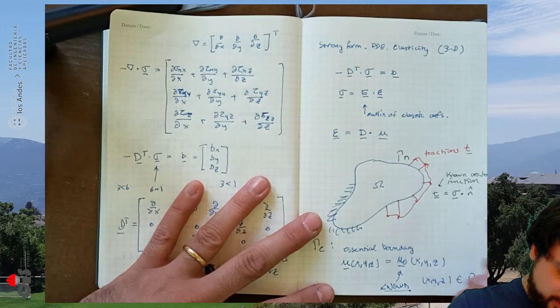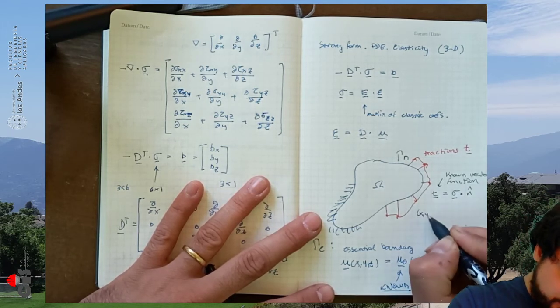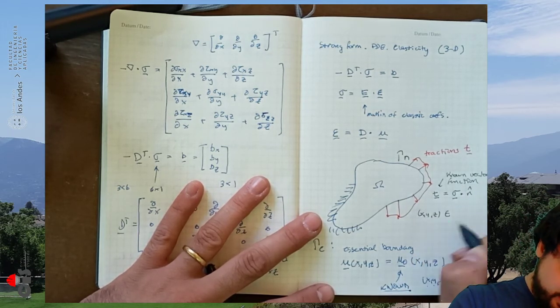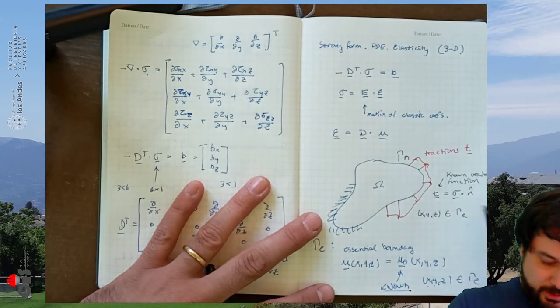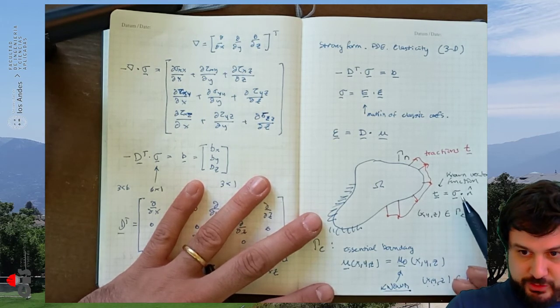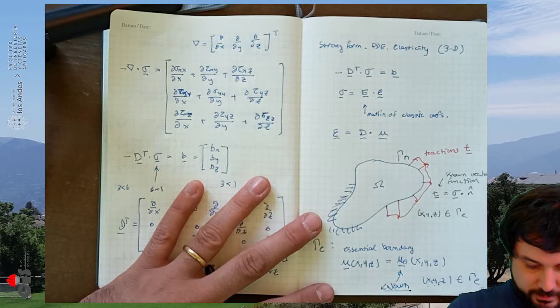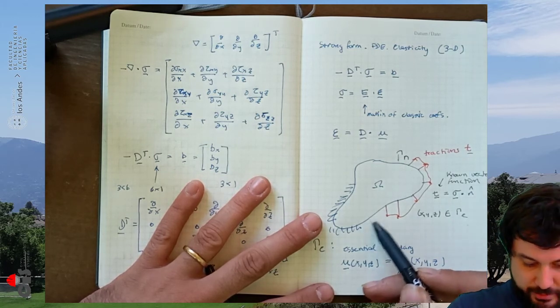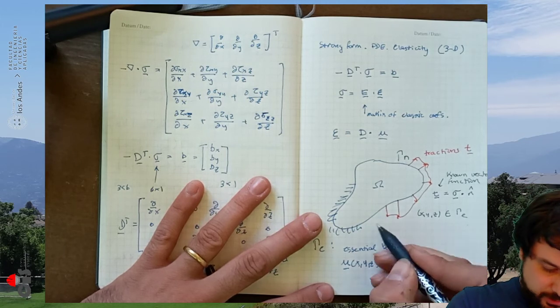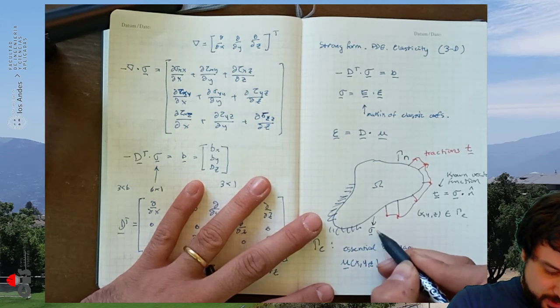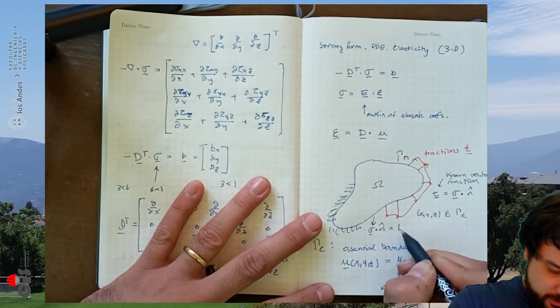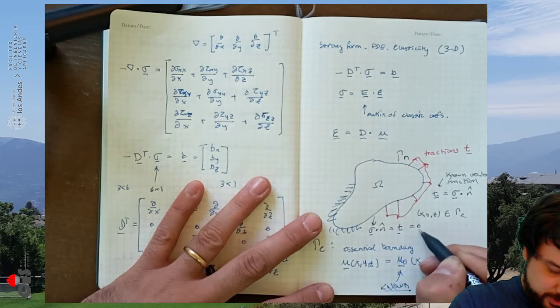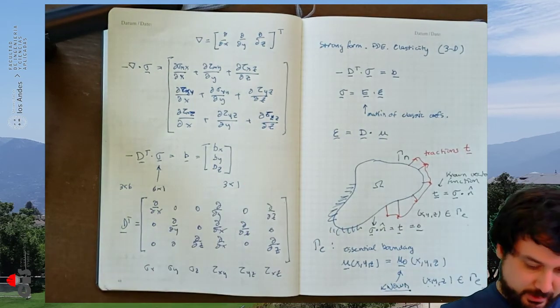So this is what binds it together, puts everything together, and xyz in this case is in the natural boundary. Yeah, and if you have 0, that's fine, it's 0. You cannot have an empty one, so this is still part of the natural boundary. The only thing there is that sigma times n, the traction vector, is equal to 0 wherever you don't have any loads defined.